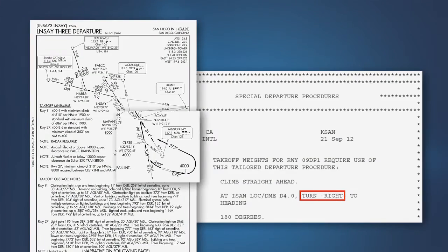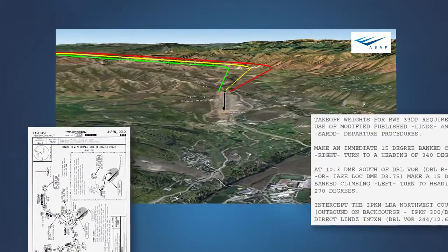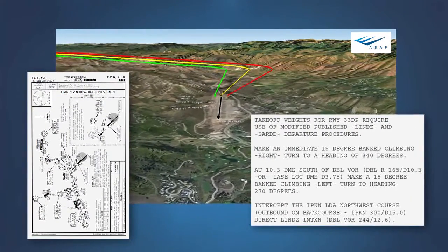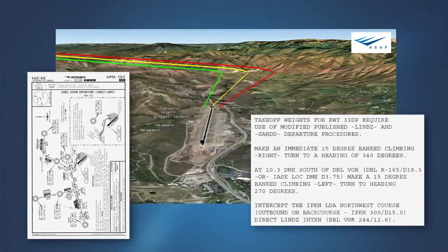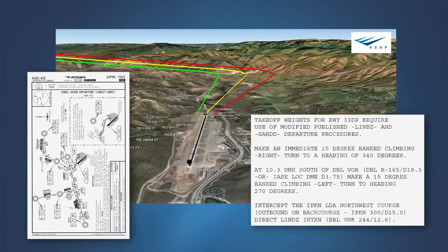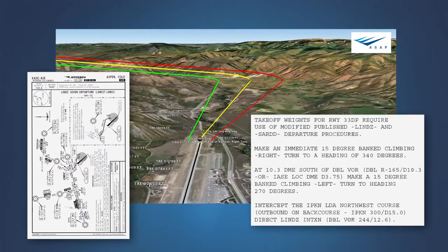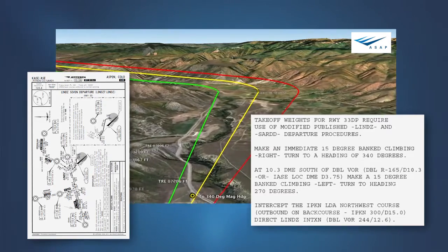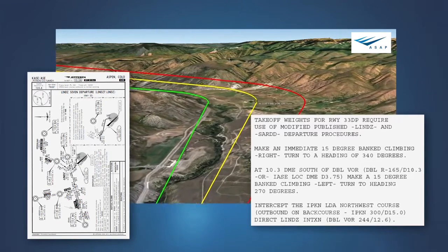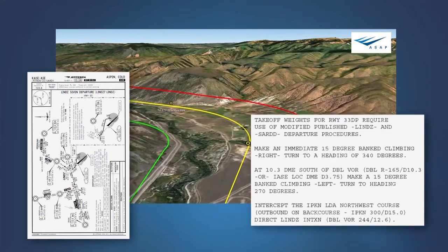The question of what action a pilot should consider or take when the engine failure procedure differs from the IFR departure procedure is worth addressing. At terrain-challenging airports like Aspen, the engine failure procedure typically conforms to the IFR departure procedure for the takeoff runway. However, modifications may be necessary to identify the start of any turns using precise geographical references instead of the altitude crossings that are frequently used on SIDs and ODPs. If it is not already available, it may be appropriate for the operator to request an engine failure procedure that does align to the SID or ODP to the extent necessary for the airplane to reach the IFR en route environment. As we saw at Aspen, this may involve the use of a conveniently located holding pattern.